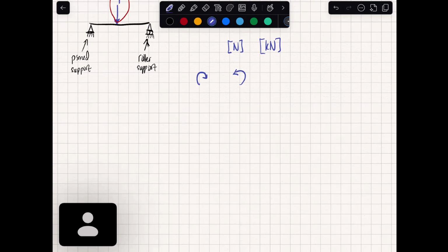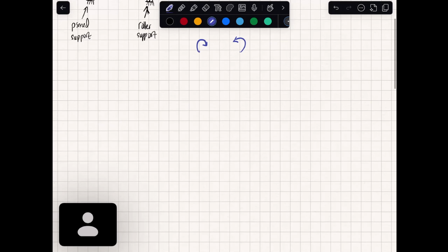First of all, we have point loads, which is also called concentrated loads. For example, if you have a concrete slab like this, and you have a column, so this column goes up. So we have a column like this. And this column is carrying some type of load from above. So it will be a very concentrated load on the edge of this slab in that case. So that is what a point load is.